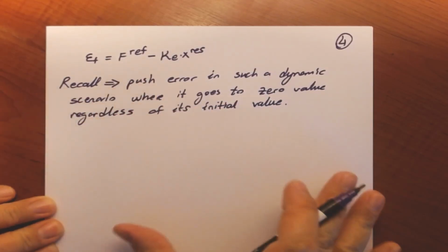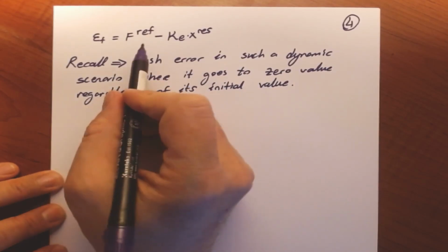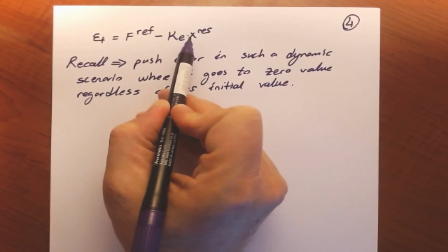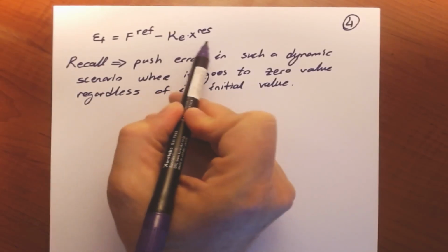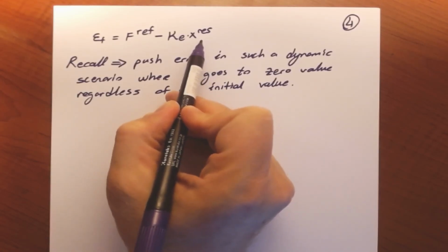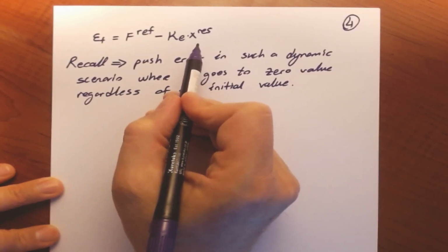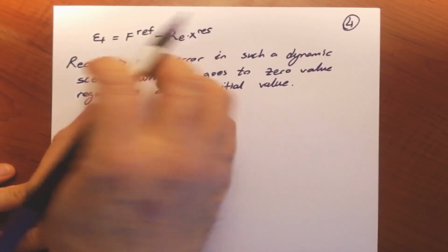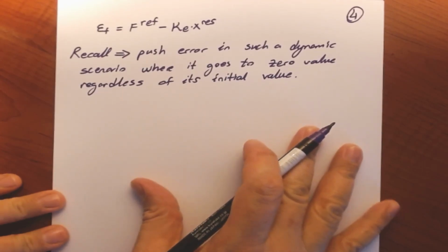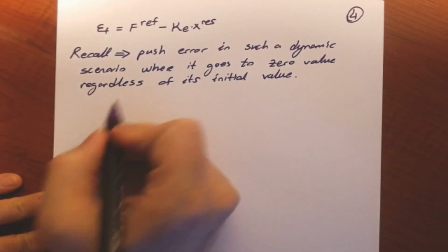If you remember, we were able to do this through differential equations, and here we have the x response, so we have a first order system. There's no velocity component here in that equation, right? If you recall from the pure position control, an equation in this form has to be differentiated 2 times so that we can extract the desired acceleration, that's the response acceleration for a system with disturbance observer.